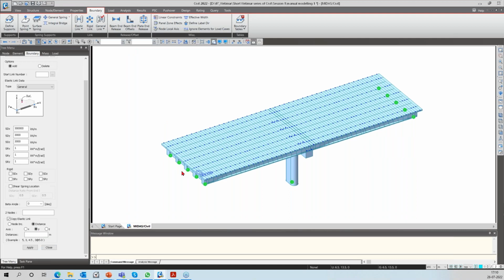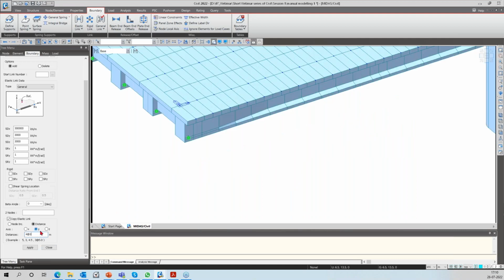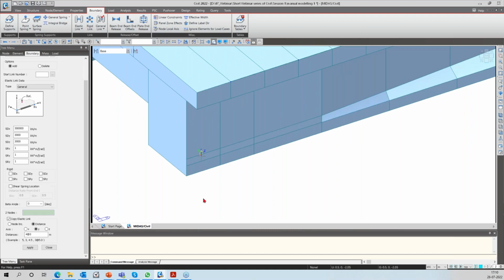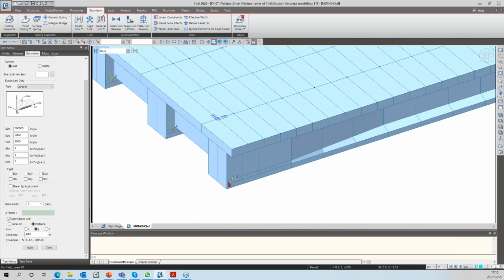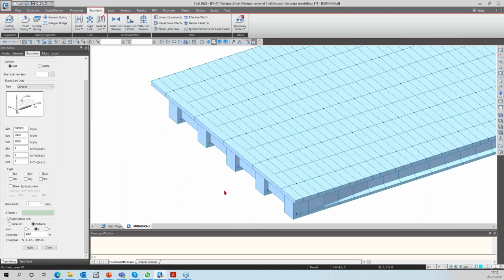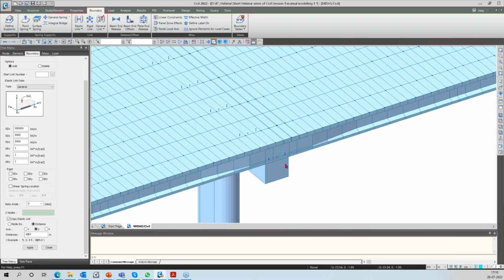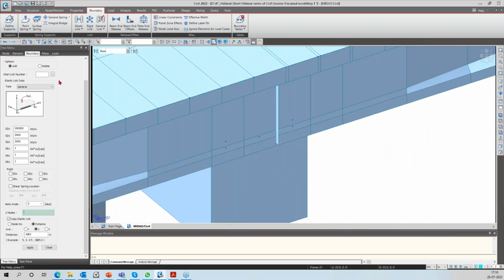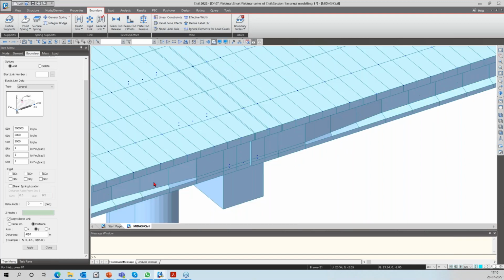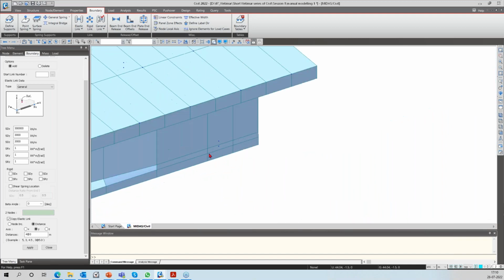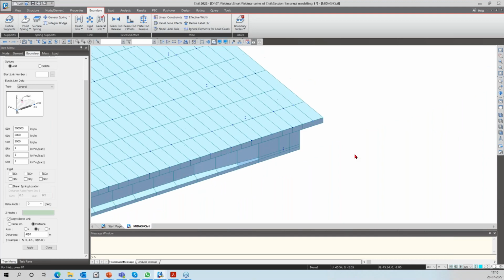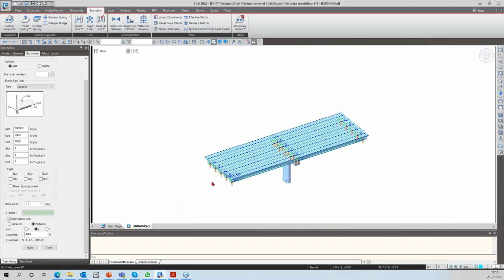and I'll go for this Y direction and start providing the information like 4 at the rate 3 meters distance apart. And then I'll go ahead, click on one node and the second node. So this link that I have generated right now is copied to all the nodes that are spaced at 3 meters apart 4 times. Same thing, I'll do it over here. And that's in this way. And lastly, over here. So we are done with the bearing information.